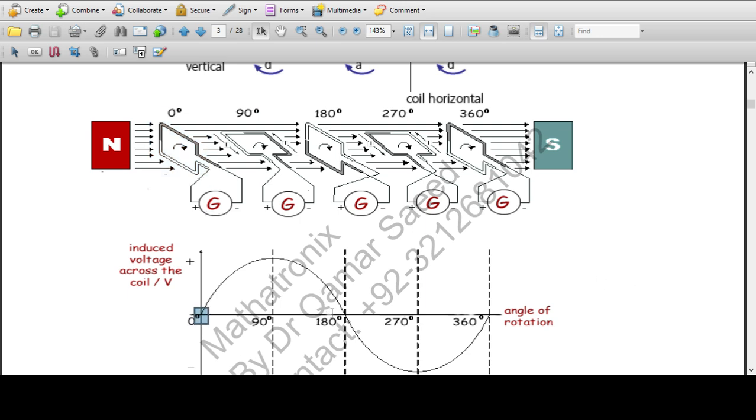This is this point, this one and this one. So these 3 points are where the fields are in parallel. The force is in this direction and the fields are also in this direction, while on the other side the field and this conductor's movement are perpendicular to each other, where we get the maximum EMF, and between these values the EMF occurs in the range from 0 to 90 degrees.